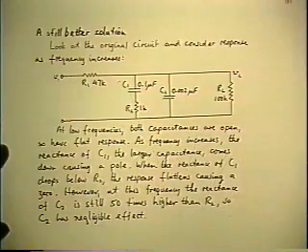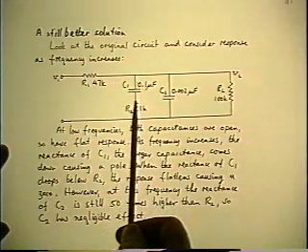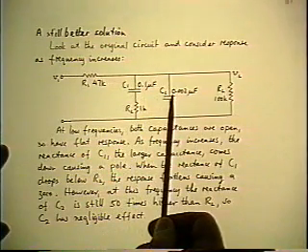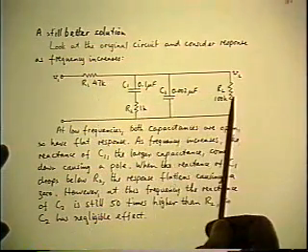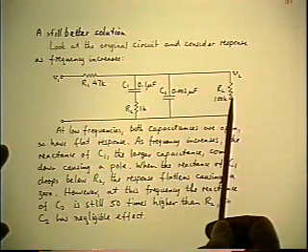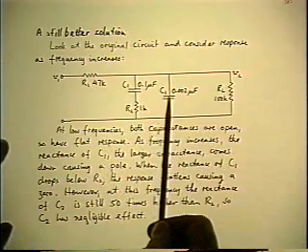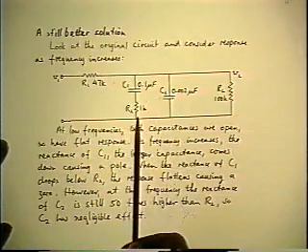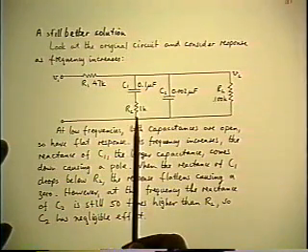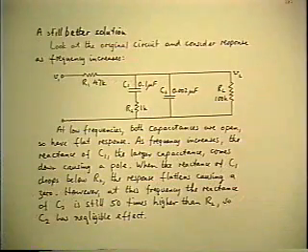At that point, the circuit is now such that C1 acts as a short and C2 is still open. So you get another flat gain corresponding to a different resistive divider, where R2 is in parallel with RL in the bottom branch. Finally, at a still higher frequency, the reactance of C2 comes down to be about 1K. Then it causes the gain to fall off again. From its already lower value, it falls off even more. But only C2 is doing anything in that frequency range.